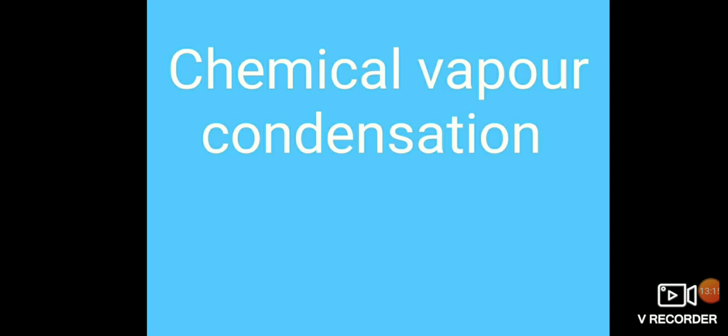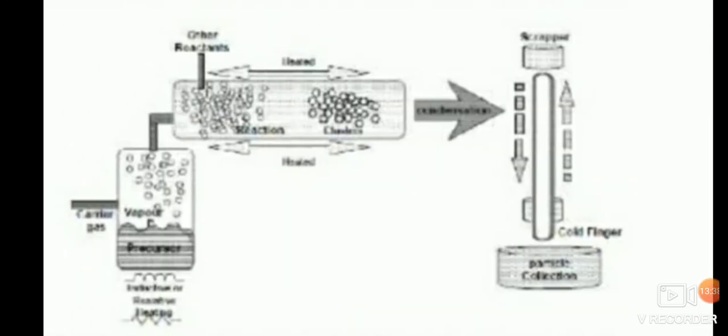Depending on the processing parameters, nucleation of nanoparticles is observed during chemical vapor deposition of thin films and poses a major problem in obtaining good film quality. The original idea of the novel CVC process, which is schematically shown below, was to adjust the parameter field during the synthesis in order to suppress film formation and enhance homogeneous nucleation of the particles in the gas flow.